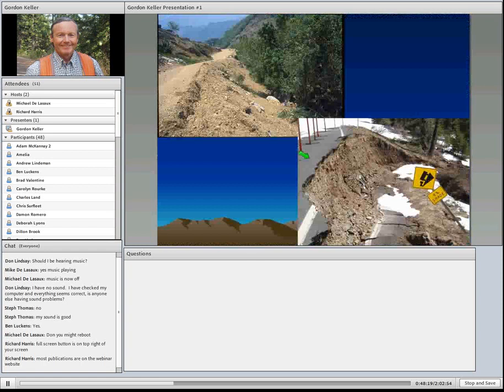And there's probably two main reasons why you get fill slope failures. One is just over steep slopes. If you put on maybe a 60, 70, 80% slope, it's not going to stay there. And it's very difficult to compact unless you've built in some terraces. So it's over steep slopes like side cast, which is an old style of construction. And the second one down here is drainage. There was a big spring coming out from underneath the road here. So those are two things you want to watch for.